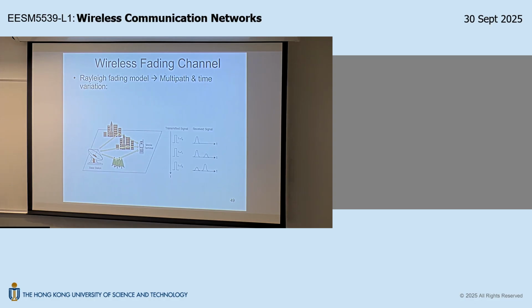Let's consider a receiver point at a distance of d. Let's imagine drawing a virtual sphere centered about this transmitter point. By symmetry, because the transmitter is radiating radio waves in all directions, if the transmission power is Pt, each point on the surface of this virtual sphere will have the same received power density, because it's isotropic.